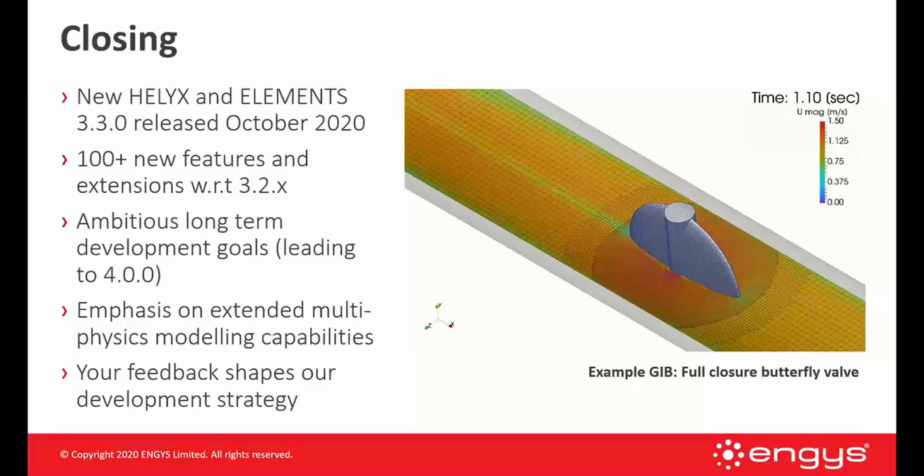Gotcha. Yeah, absolutely. In terms of runtime visualization, what is the performance hit per iteration, I'm guessing, when you output an image? The answer is it depends on which kind of image you are creating. If you are creating something on the internal volume mesh, this takes a little bit more to load than a surface mesh or a geometry. So based on our tests, it varies from 10 to 20% overhead.